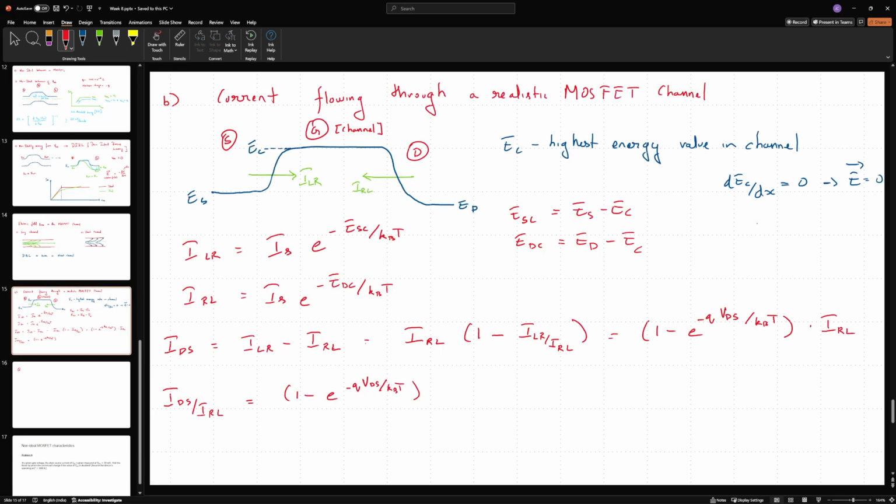Now the next quantity that I will try to evaluate is Q, at the point corresponding to x equal to 0. This point where I have the highest is the point that I'm going to call x equal to 0. In a realistic scenario, I may even have some DIBL and other threshold effects affecting my channel, but I am considering this energy here for present purposes. I can just model this as a very large junction with a very wide depletion layer. Even then these Schottky equations will hold.